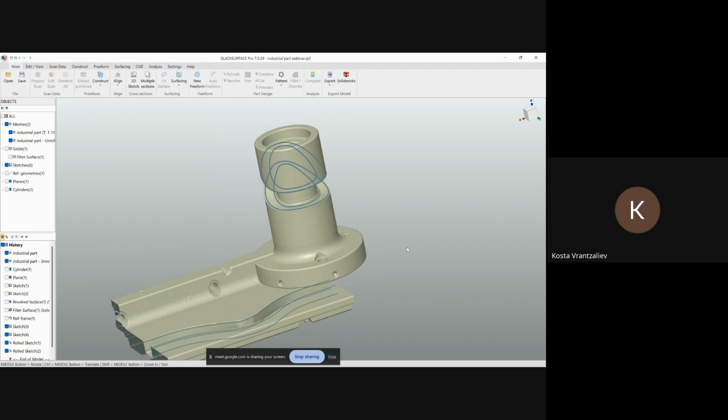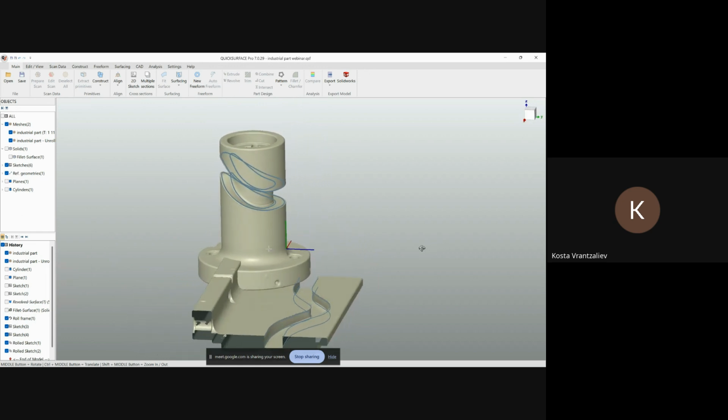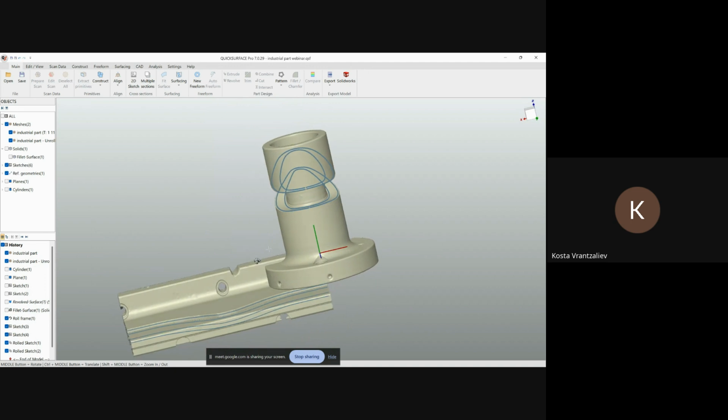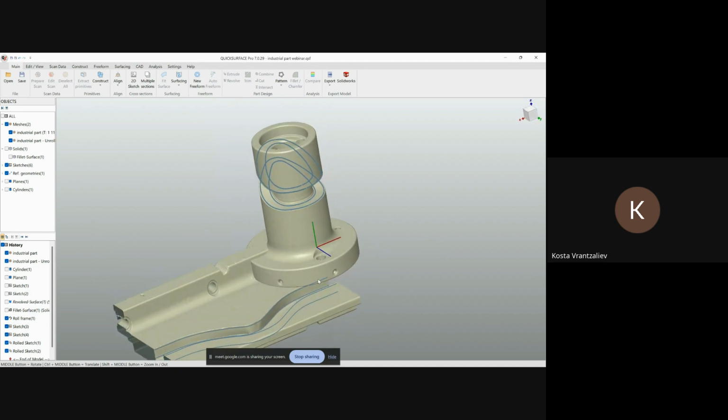If you open the frame on the left side in the feature tree, this is defined just from the cylinder, and this is what maps the 2D space into the cylindrical space. That's why when you do 2D sketches, you need to do this in the XY, and the length of the sketch needs to be the circumference of the cylinder, how it's unrolled.